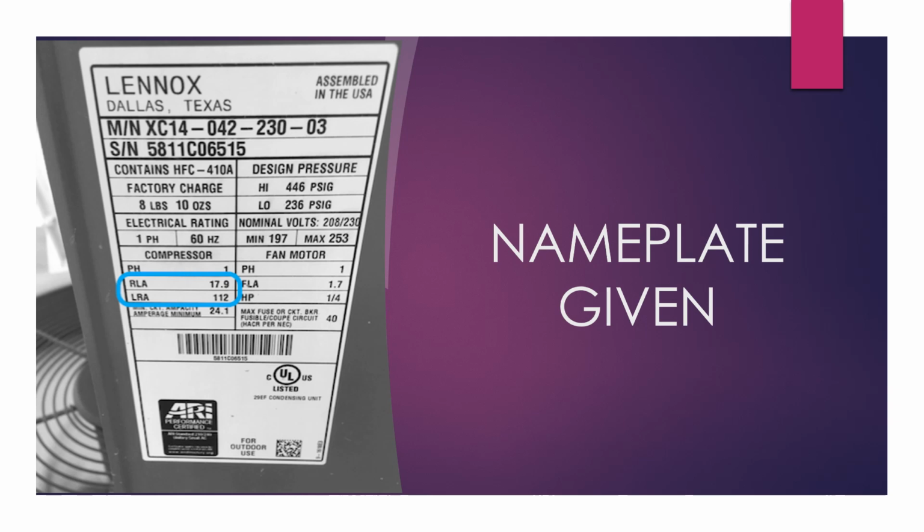This is a 3.5 ton motor compressor, and the RLA, or the rated load amperes, is 17.9, and the LRA, which is the locked rotor amperes, is 112 amperes.